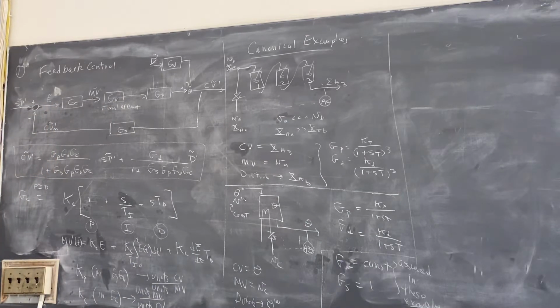What I'd like to do now is look at what happens when I combine these, because we said there were pluses and minuses to each controller. For the proportional controller, it was pretty fast. It lowered the time scales, but it could make the system unstable, and it never gets rid of the offset. So it has good and bad. It's like with people: there's no perfectly good and no perfectly bad. They have good points and bad points. The good point is it gives you a speedy response. The bad points, you could overdo it, and it doesn't get rid of the offset.